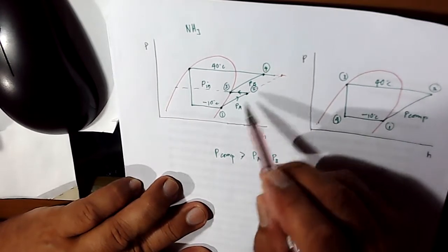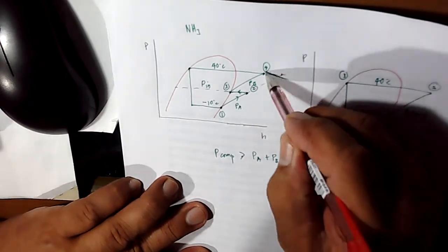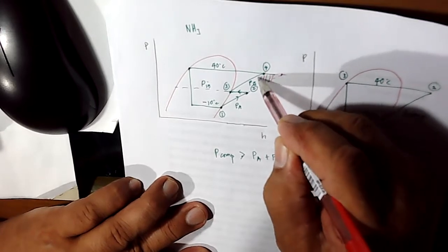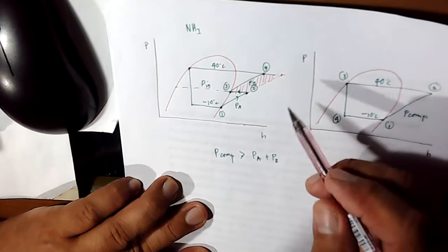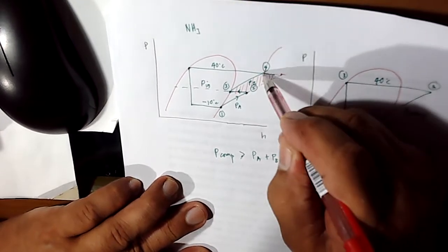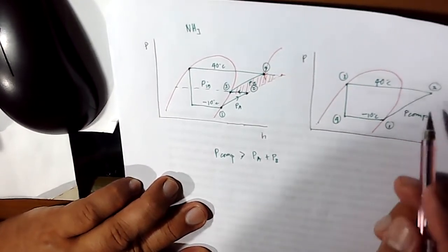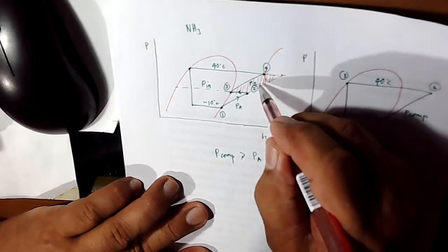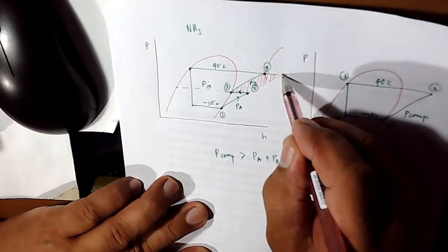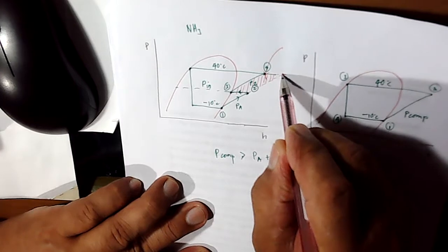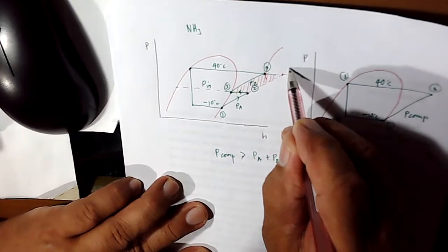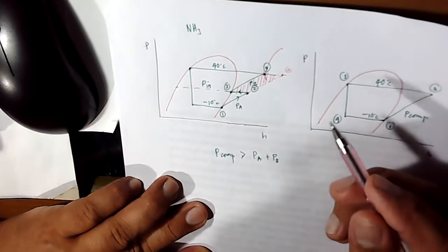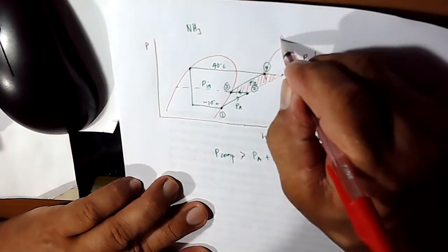The area of compression is reduced by this much using two small capacity compressors. It means that this area now, if you are going to use only one compressor, this shaded area bounded by 2, 3, 4, let's say consider this as your point X, is considered as your power save.